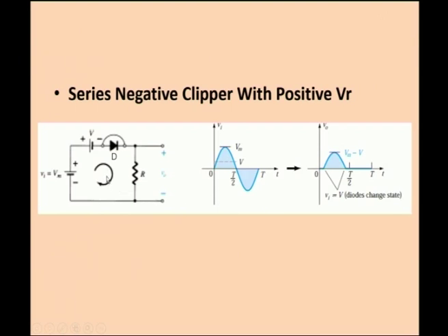So, here during the positive half of the cycle, this is the input waveform and this is the output waveform. This is the circuit. Now, we have to apply the input signal, and the instantaneous values of the input signal can be considered as DC values while applying in the circuit, and also we can obtain the instantaneous values of the output as DC outputs. We can consider both values as DC values, even though the input is an instantaneous input.